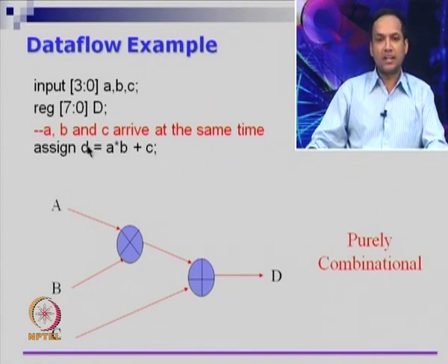So, D is actually an 8-bit number, and if you wrote something like this, so forget the declarations, if we had anything like assign D equals A times B plus C, then the implication is we have A, B, C which are the inputs and D is the output,